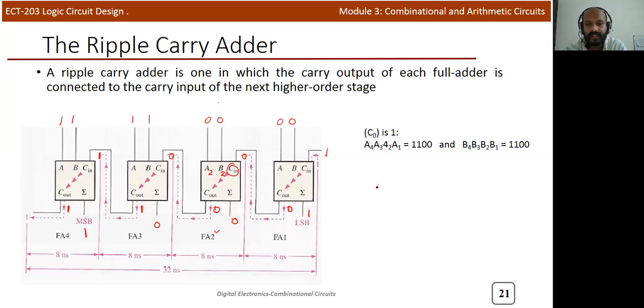It means if you use any digital circuit to perform, let it be a full adder, for example, this is A, B and C. Assume that it takes some time to evaluate the result, and finally the result will be available only after a few nanoseconds. That delay is what we call a propagation delay. So after this propagation delay, it will reach the output of this full adder.